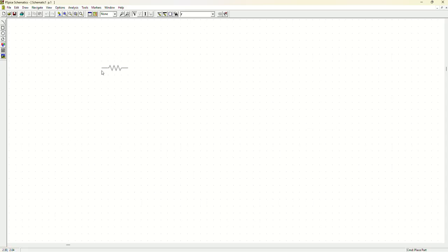In this breadboard we are going to put different components. So this is our resistor. Your resistor would remain connected with your mouse until and unless you press the escape button. The more you click, the more resistors you will get. Now suppose you would not want more than 5 resistors. So what I have to do is press the escape button. After pressing the escape button, now it is gone.